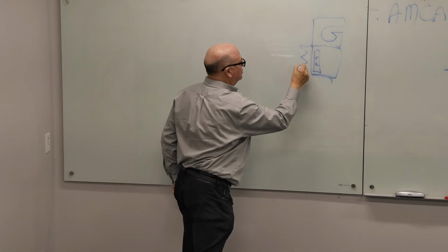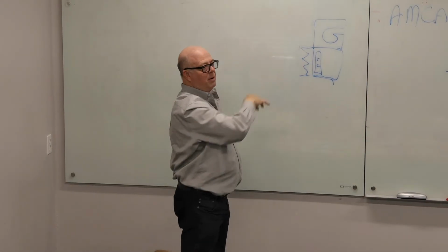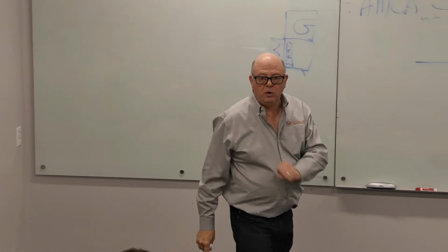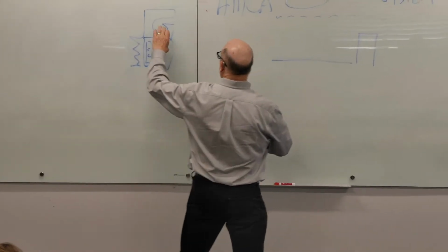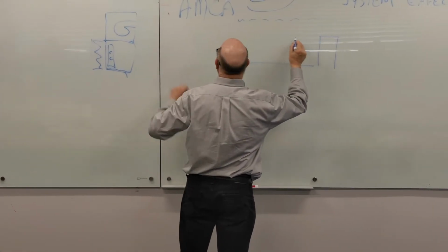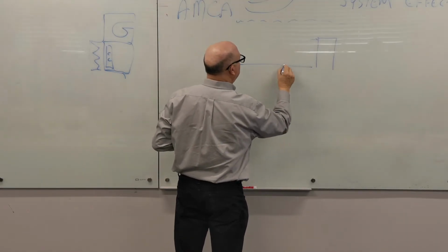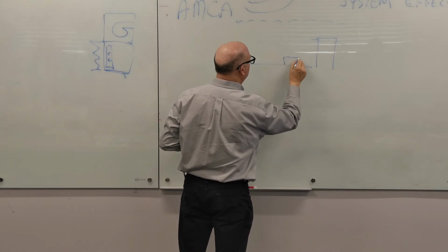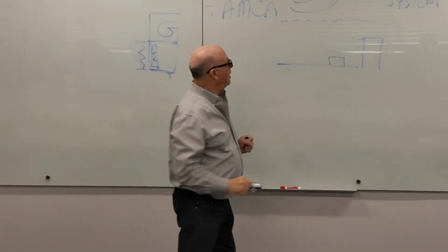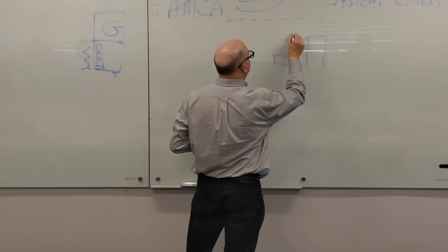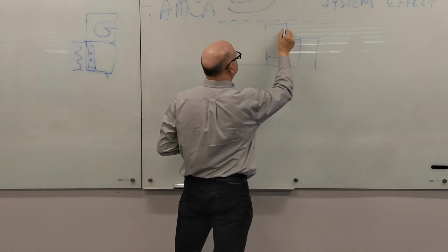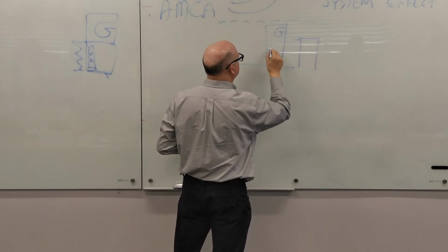We've got the filters, and then maybe some mixing box dampers or whatever. What Pete would do, this would have been blowing probably right about here. So Pete would put a stand in the room, and then he would put the vertical draw-through air handler on here so that the fan was arranged like this.